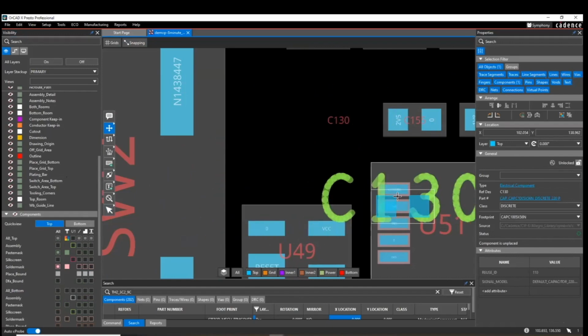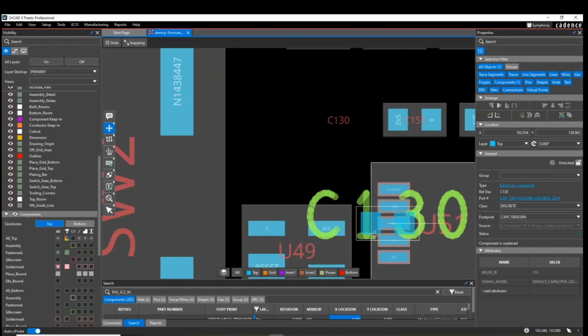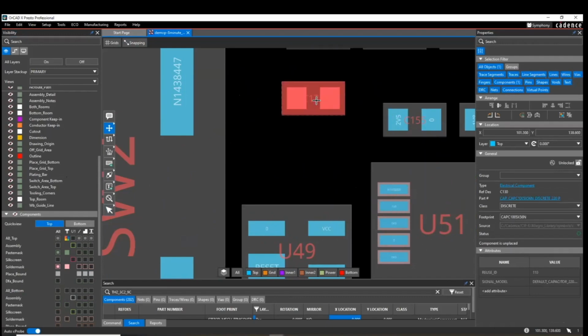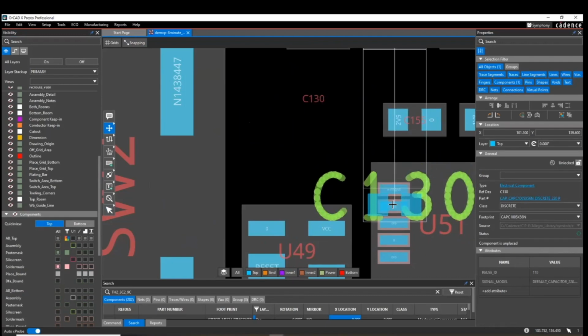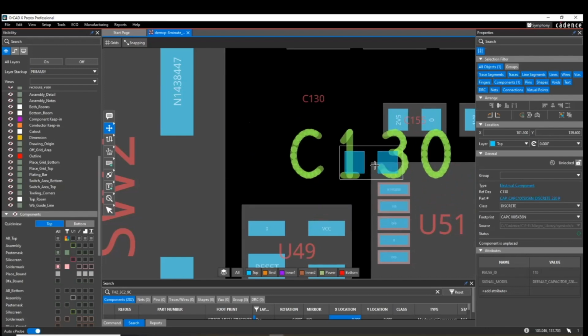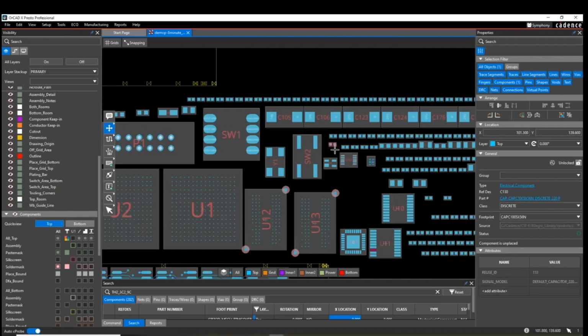And then as I move it around, it's going to snap to the other pins or the vertices or the midpoints. If you drop the part and pick it up from the middle, you're now moving it from the middle, and it's going to snap that middle point to the endpoints or the vertices. So snapping works intelligently on pickup, endpoint, put down. You don't constantly have to be telling the tool what you want to snap to.